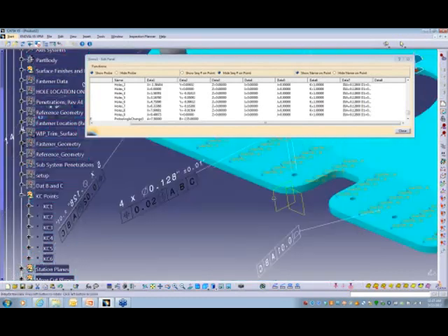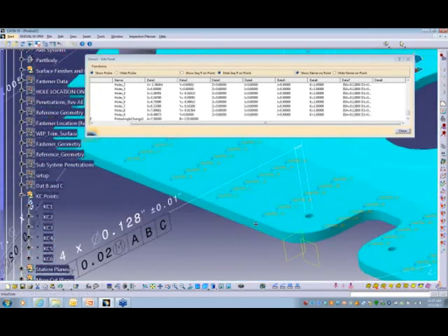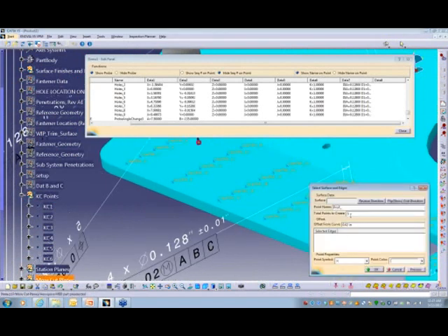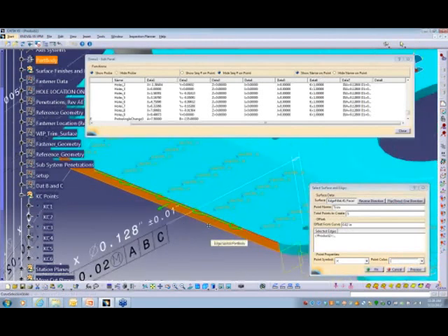We have another really slick way to put points along the trim of the part, and it's this icon. So we want to put 5 points. We're going to call these points trim. We're going to pick the model. We're going to say we want to come from outside here. We pick the edge. We're going down 20 thousandths, and we could say preview. We want to reverse that direction. So we're going to go from here to here, and we could say OK.